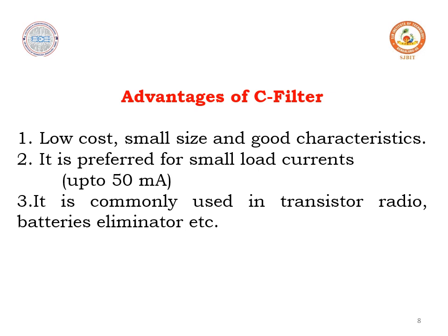Advantages of the C filter. First, it has low cost, small size, and good characteristics. Second, it is preferred for small load currents, up to 50 milliamperes. Third, it is commonly used in transistor radios, battery eliminators, etc. So overall, we can use the C filter for filtering out.